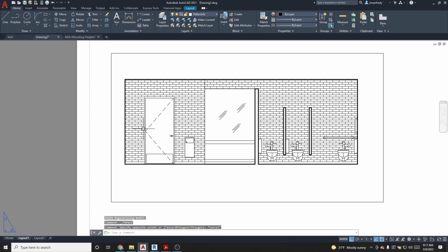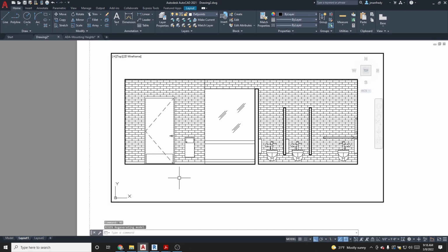So this dotted line wasn't showing up a second ago, so I fixed that problem. And how do I fix that problem? I do the following. PS LT scale, Paper Space LT scale, is set to 0. Make sure that's set to 0. MS LT scale, Model Space LT scale, is set to 0. When I click inside here and type RE for regen, that fixes this problem here.